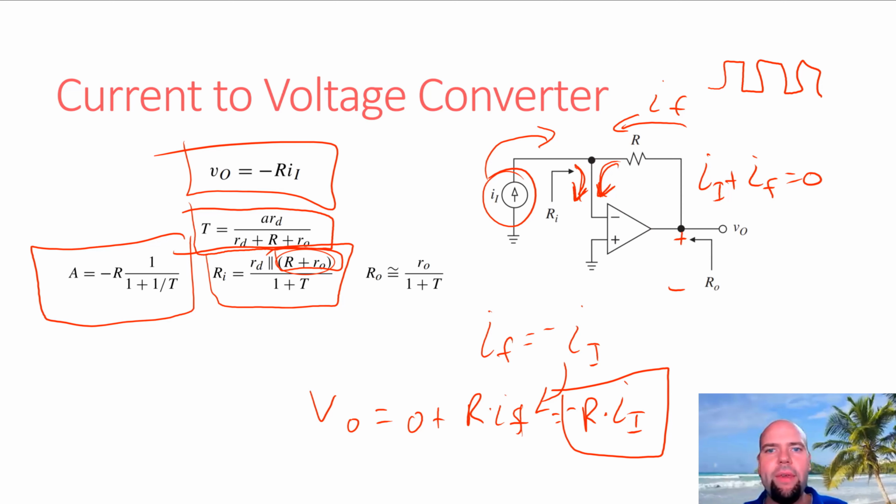Your remote control is probably putting out a pretty bright light, but you want your TV to still work if somebody's pretty far away. So there's only a very small amount of infrared light striking that photodiode. It's only producing a tiny amount of current, maybe nanoamps or less. Not only is it producing only nanoamps of current, but you want this nice sharp response.